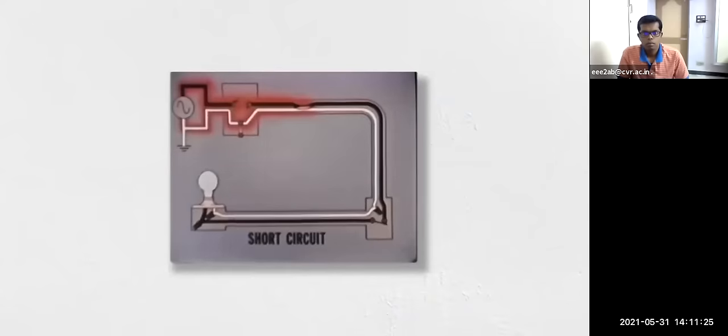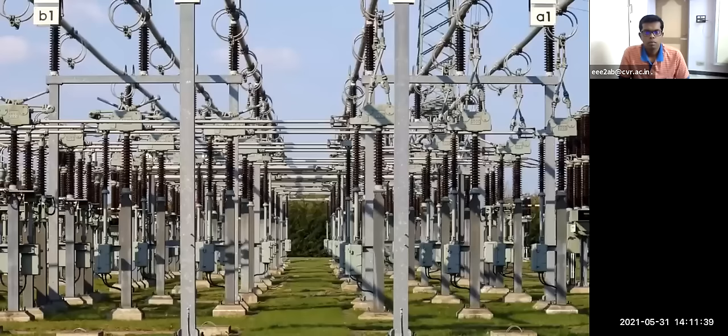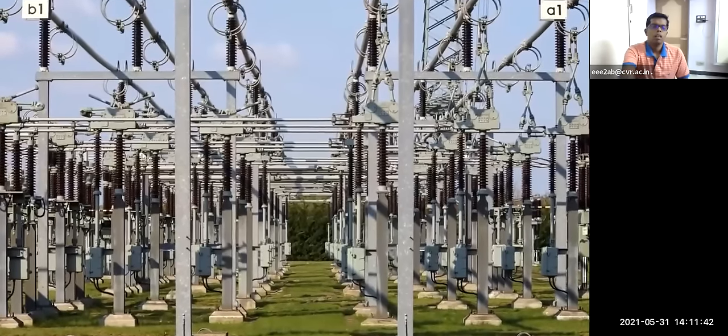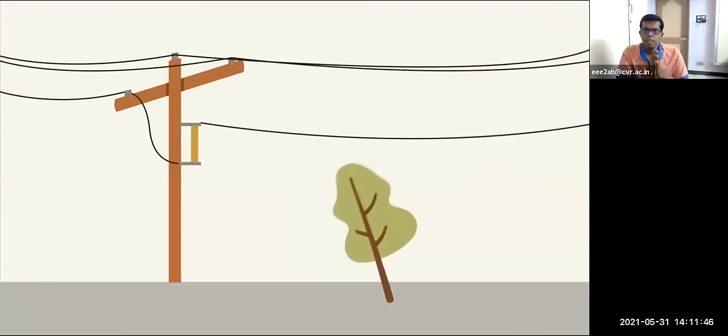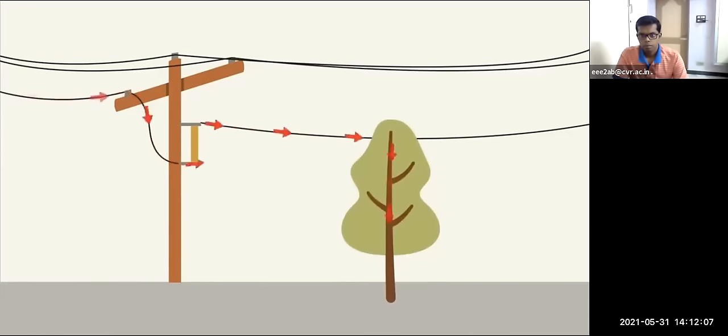When something causes a short circuit on the power grid, also called a fault, it can severely damage power lines and other equipment. Not only that, because of the overwhelming complexity of the power grid, faults can and do cascade in unexpected and sometimes uncontrollable ways, leaving huge populations without power for hours or days. Many of the ways we protect equipment from faults are handled at a substation. If any fault happens, the circuit breaker will automatically trip. If it is not tripping, you need to reconnect everything, which will take more time. One of the most common types of electrical fault is a short circuit to ground. This type of fault creates a low resistance path for current to flow and leads to an overload of power lines and equipment.